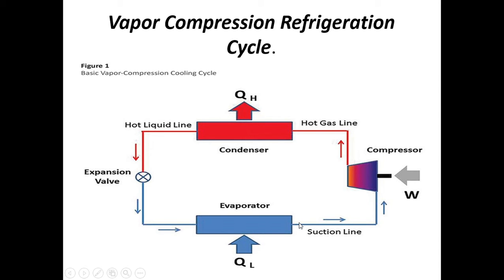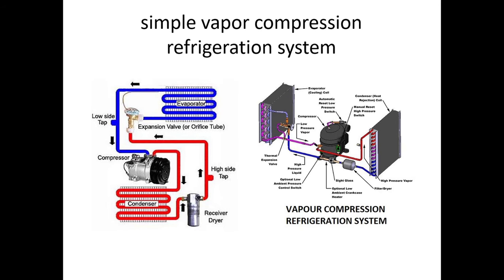Next, after the evaporator, vapor refrigerant comes out. That refrigerant is sucked by the compressor, which increases the pressure and sends that higher pressure refrigerant into the condenser for the next cycle. So the same cycle repeats. Now this diagram will show you the various pressure sides and components.